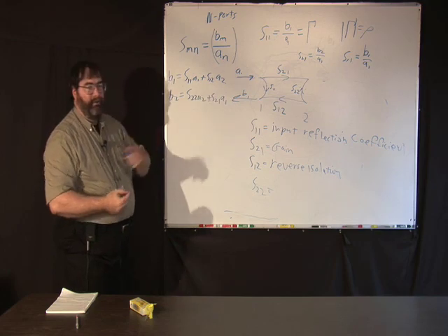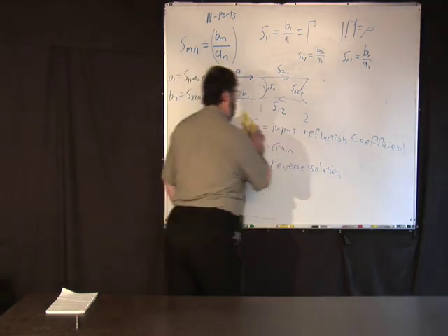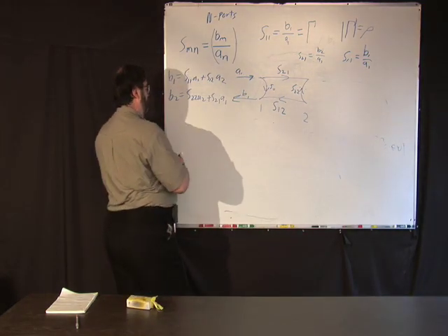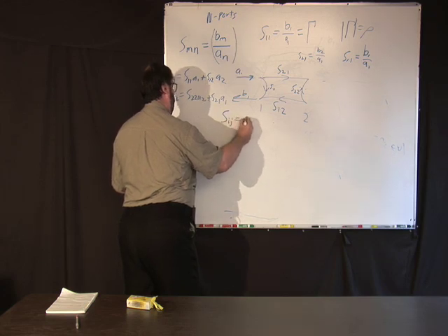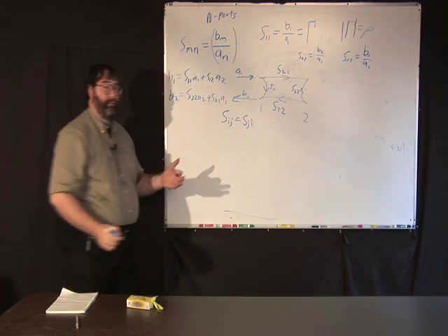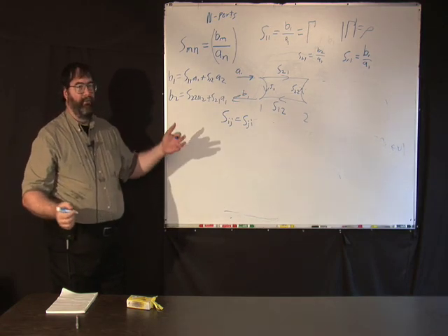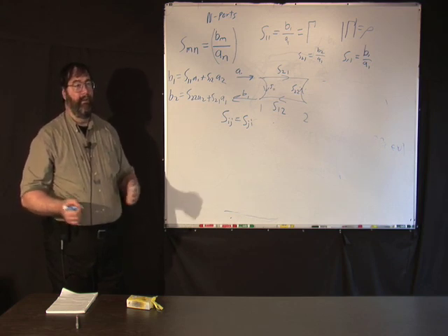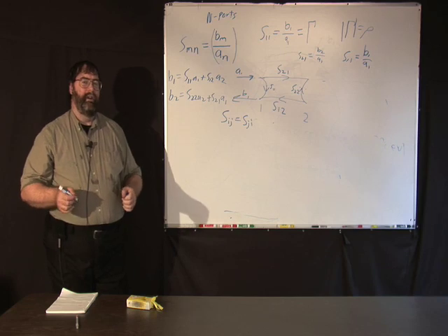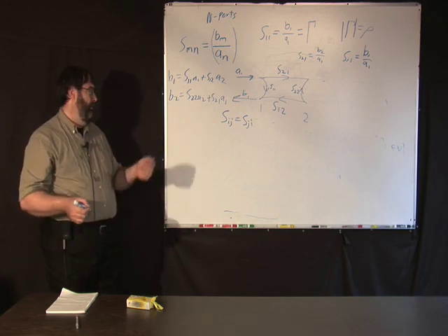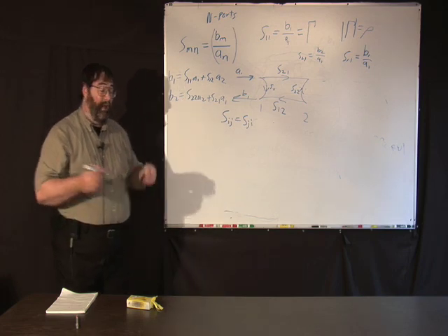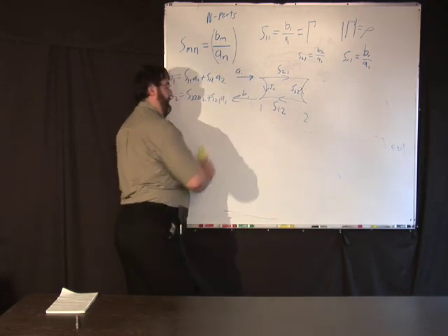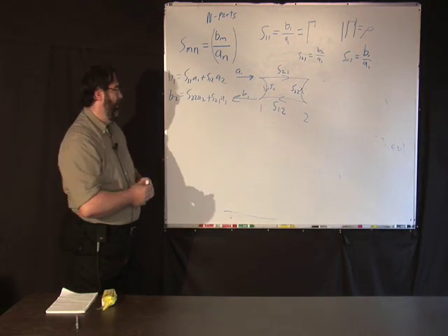A device, a two-port device especially, is called reciprocal if Sij equals Sji. That's called a reciprocal two-port network. Or in general, for an n-port network, you can have a reciprocal network. Most networks are not reciprocal. In fact, at some level of accuracy, all networks are not reciprocal, but for a lot of practical purposes, a lot of devices are reciprocal. Because if you're going to get down into parts per million, they're not going to be reciprocal for any type of device.